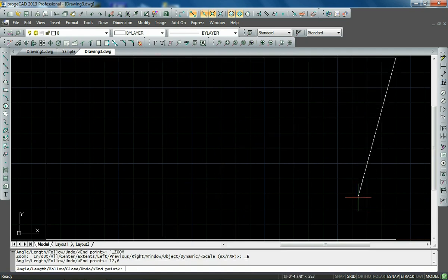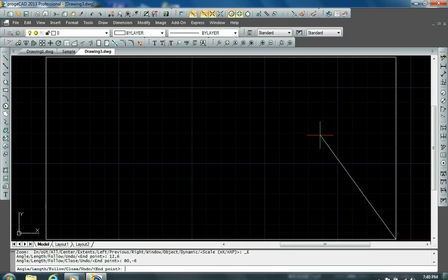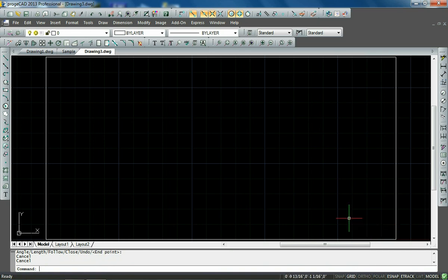For the last point, we will enter it another way to show you another method. Instead of entering the coordinates from 0, 0, or the origin, we will just move relative from the last point down 6 inches. To do so, we will start with the command as an @ symbol. Enter @ 0, -6, indicating relative coordinates. That is 6 inches down from where we were our last point and 0 inches left or right. We now have the box forming the outside.